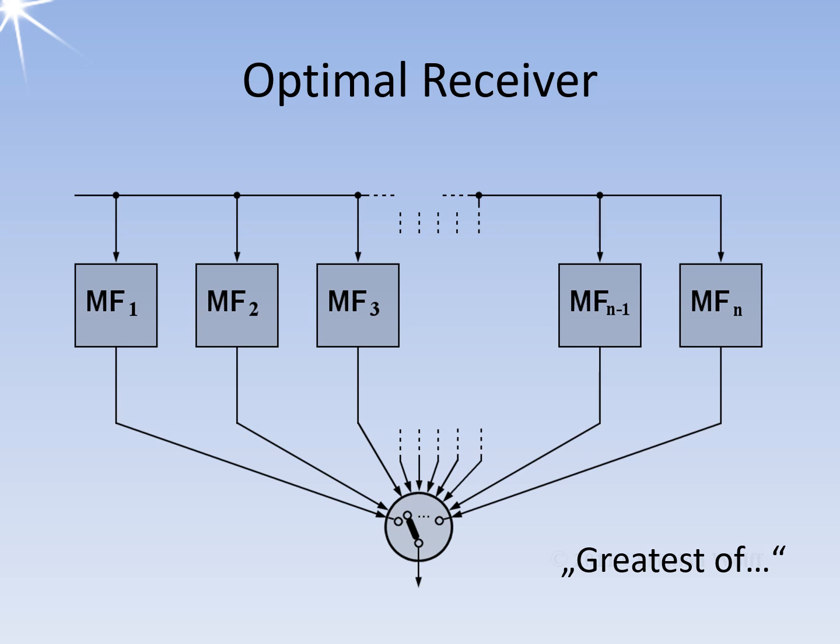In principle, a matched receiver for radar does exactly the same as the matched filter for radar. Various parallel channels with different receiver parameters, such as different bandwidths of the second intermediate frequency, provide an optimal signal-to-noise ratio for any of the targets under the given receiving conditions. The signal with the best signal-to-interference plus noise ratio, SINR, is then selected from the parallel results for further processing.